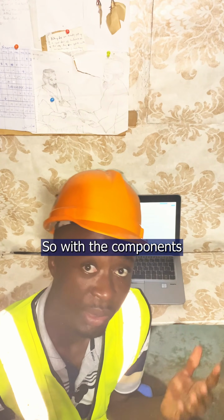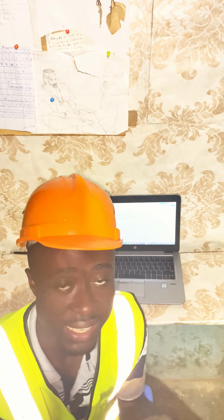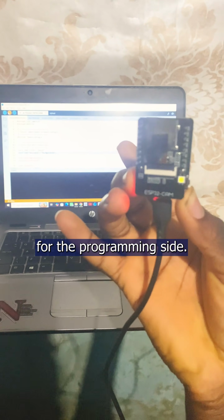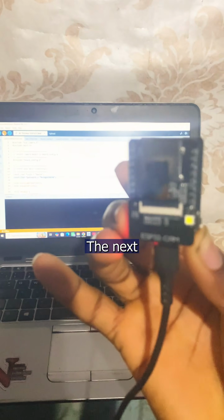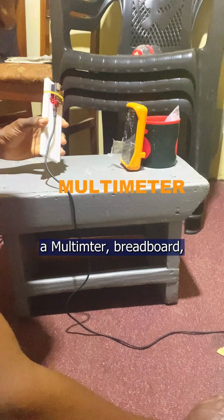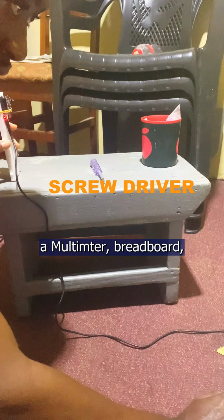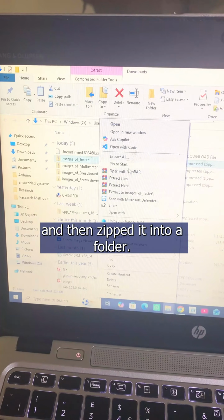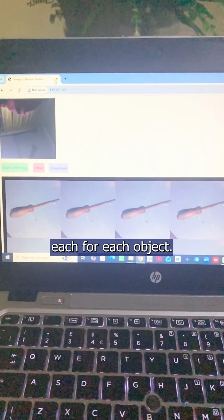With the components being ready, the next thing I did was setting up the ESP32 board within Arduino IDE. I installed the necessary libraries I would be using for the programming side. The next step was collecting images for training the model. I decided to use a multimeter, breadboard, neon tester, and a screwdriver, just these four. I captured the images with the ESP32-CAM, then zipped them into a folder. About 100 images for each object.